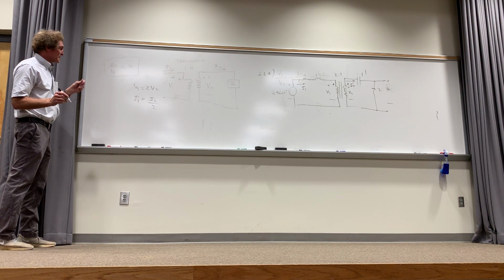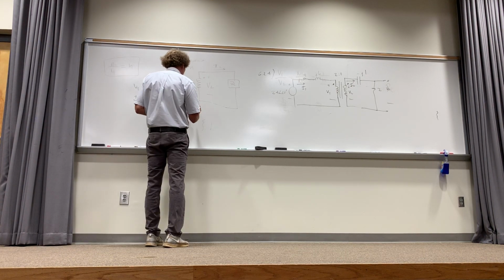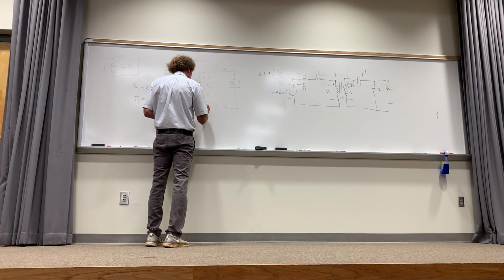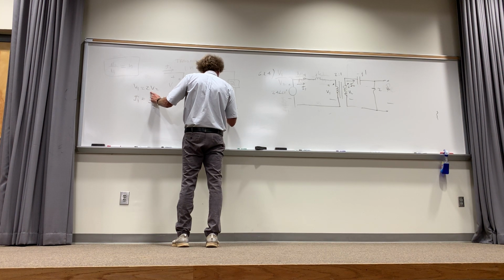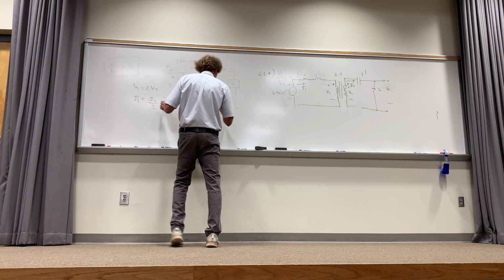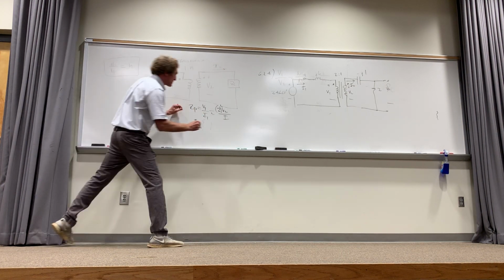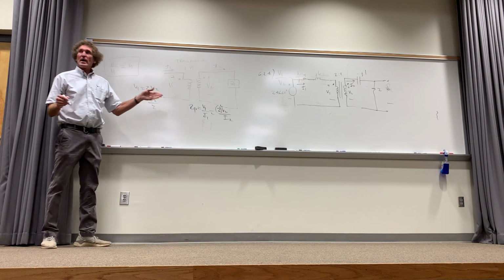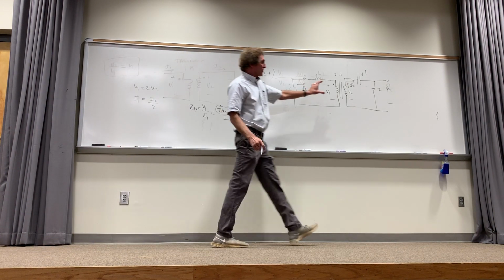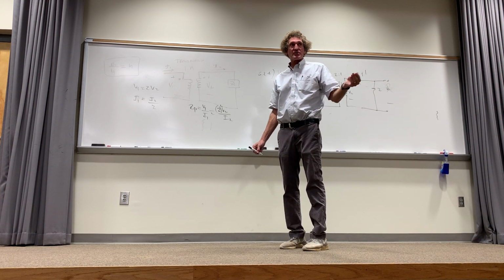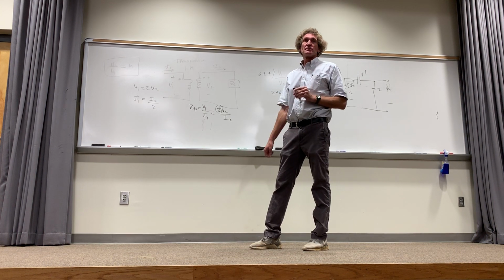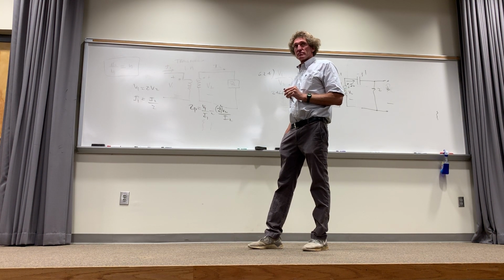Now, take a look at this. When I take V1 over I1, I get Z1. That would be the Z of the primary, V1 over I1. Well, what is that? That's 2 V2 over I2 times 2, or it's 2 squared V2 over I2. Isn't it, class? What is V2 over I2? Well, V2 divided by I2 is the second impedance. I'm trying to make sure I show you this. So, yes. For this ratio, it's V1 over V2 equals N1 over N2.